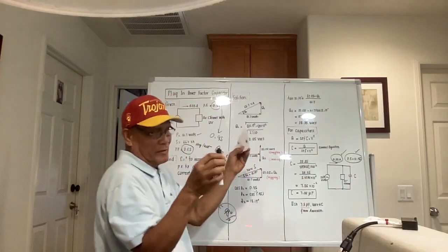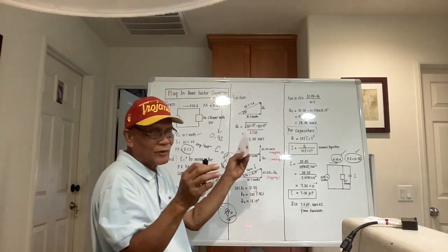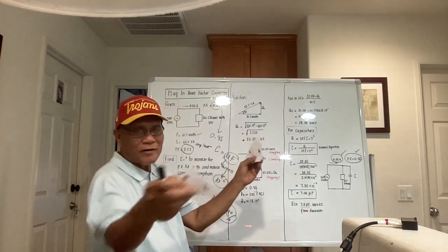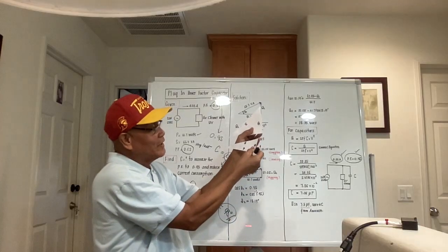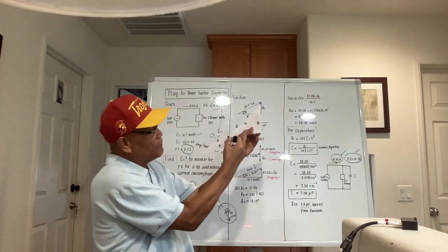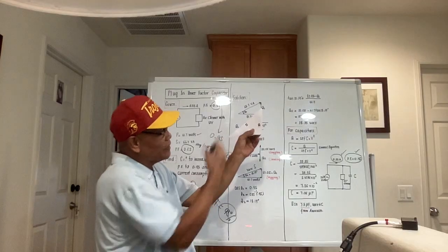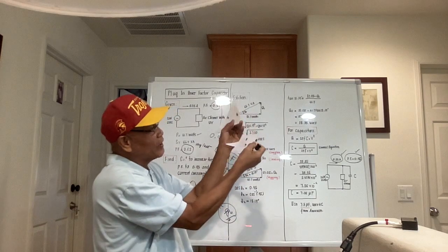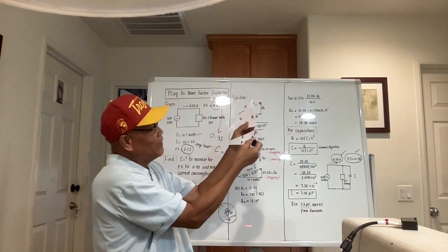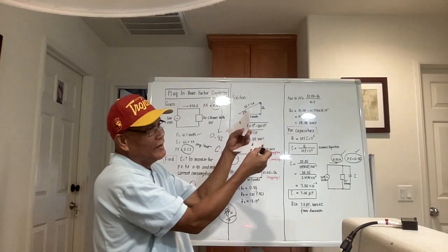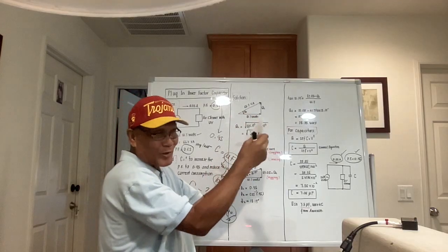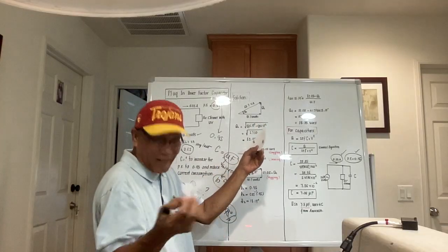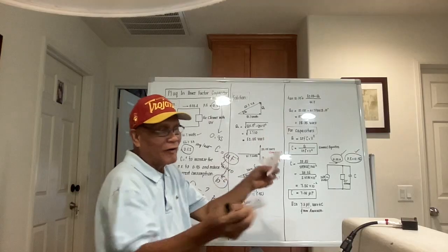And to place a capacitor, we must know the exact value of the capacitor. Okay? So in an AC circuit, for those who are not electrical engineers, the power triangle is actually very important. This is the power triangle of the load without the capacitor, and this is the power triangle of the load with the capacitor. It's smaller now. The hypotenuse is actually smaller. So if we compute its current, of course, the current will be smaller. And if the current is smaller, we reduce our electric bill. Okay, I will try to continue.